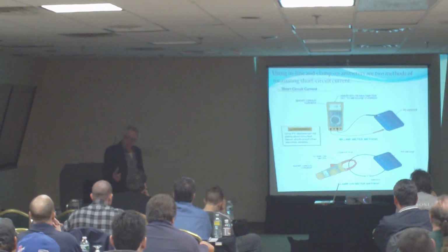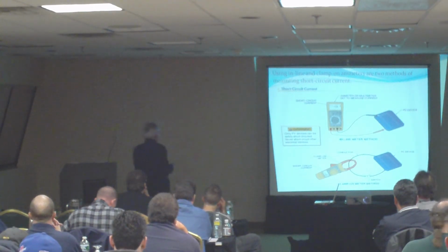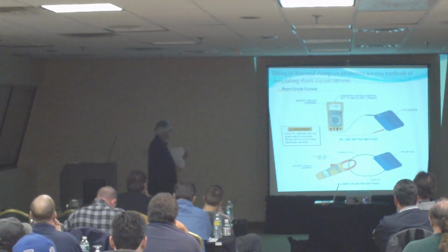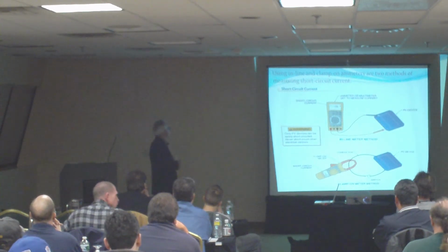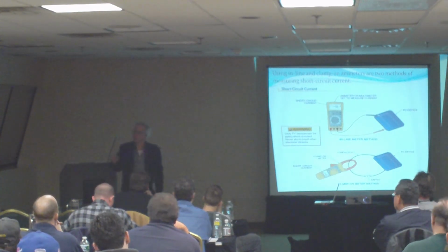Now, a couple of things, and we put that note in here. It says only photovoltaic devices you can short up and measure the short circuit current. And it says in here, don't measure any other devices like that. Is this clear? Yes, sir.